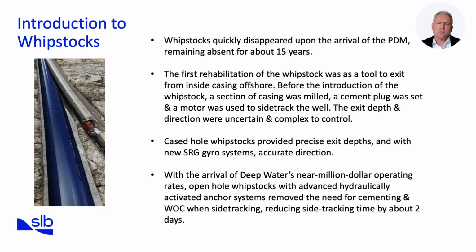In deep water, where daily operating costs could reach $1 million, modern open-hole whipstocks with hydraulically activated anchors save days by eliminating cementing and waiting on cement. Although these systems required specialized tools and personnel, the cost was easily offset by the time savings. That said, open-hole whipstocks tend to have limited use onshore due to cost.